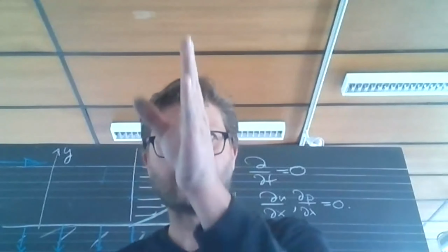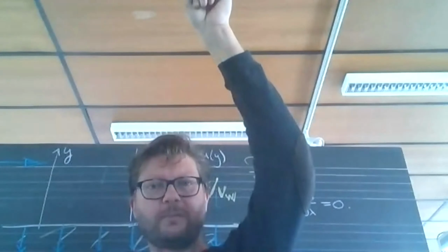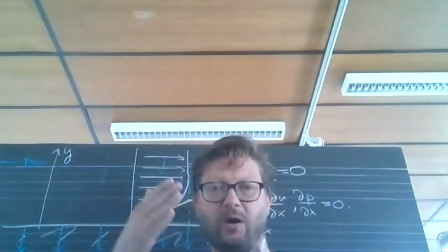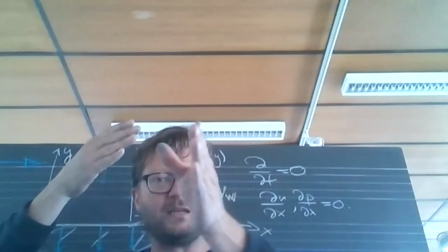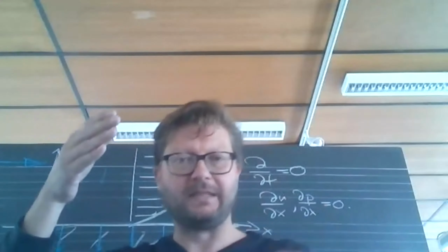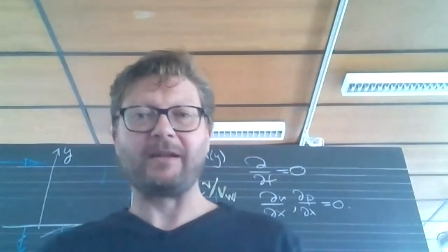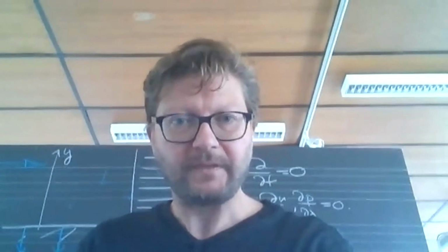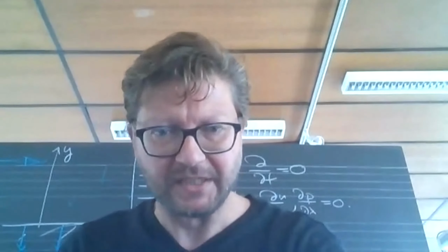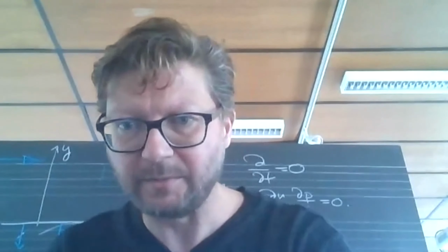So on the surface of the water, you have a perceived wind speed in the direction of your boat, and up on the mast, you have a perceived wind speed from the direction of the wind. So obviously, there must be a rotating direction of wind speed, and this with changing velocities. So that's a classical three-dimensional boundary layer. And of course, the description of these boundary layers becomes increasingly difficult because, well, in 3D, things tend to be more difficult.